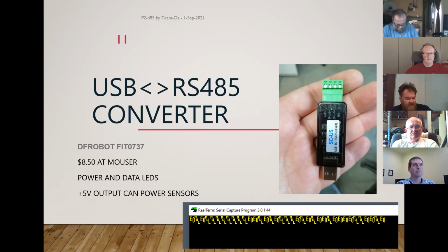which we have, which is this unit here. This has been kind of half disassembled, but it comes in a long tube, and you can see there's the RS-485 and voltage connections there. There's a dip switch for setting the address. You can have 255 of these on a network, and there's a little sensor, similar to a Sensirion sensor, at the end there for reading the temperature and humidity, and a microcontroller here for translating that into meaningful RS-485 signals.